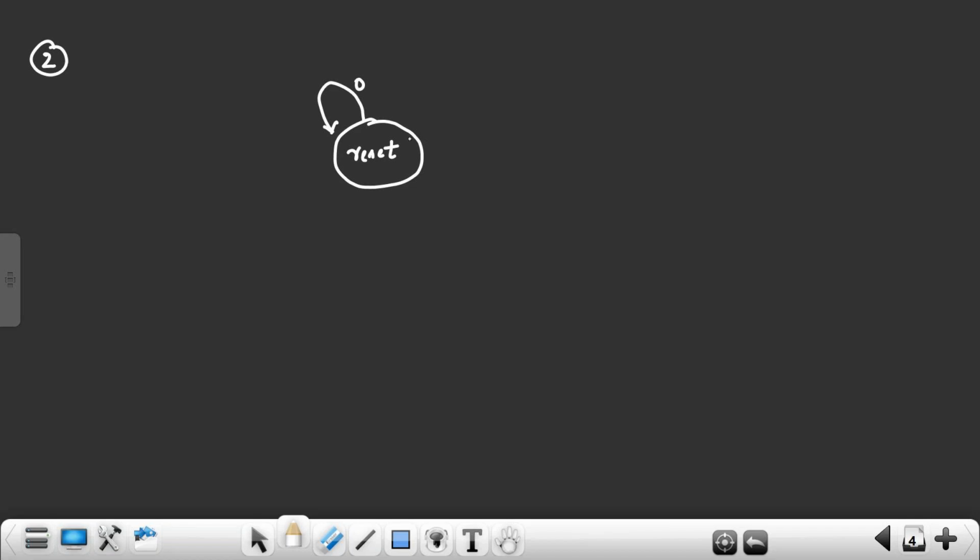When I get any input, like logic 1 as input, I go to the next state. Logic 1 input means when the card is inserted, some intermediate sensor will generate a logic 1 signal to my IC. My IC will push this into the next state. What is the next state? The next state is the pin entering state.